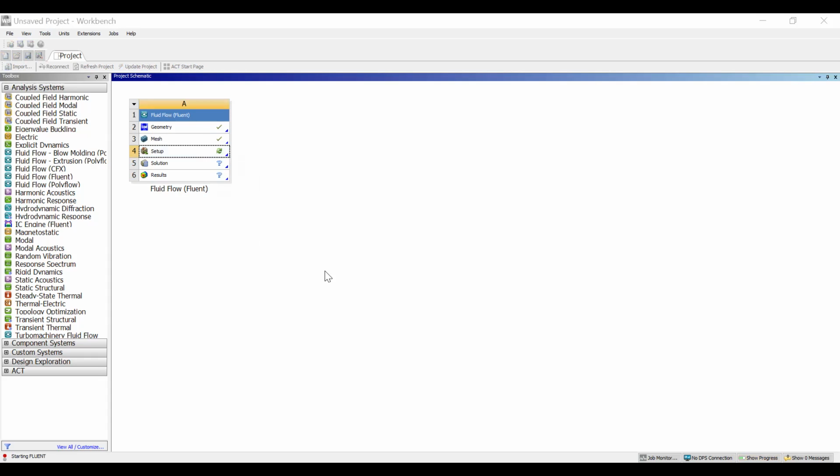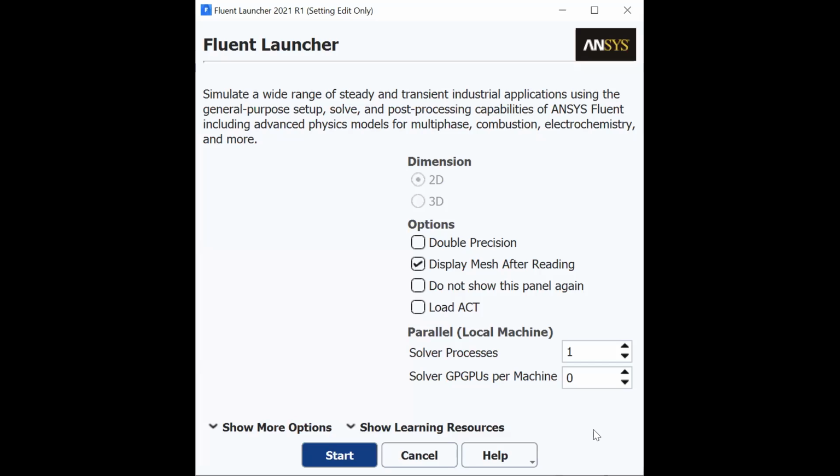We're going to actually open Fluent. I'm not sure if you can see this first part that's opening up here. I'll share it in just a second. There we go. You can see these options open up. We're going to do double precision. That's going to give us the best results, the most precision and accuracy. Change this to 4 just to make our computing lives a little bit easier. And we'll hit start.